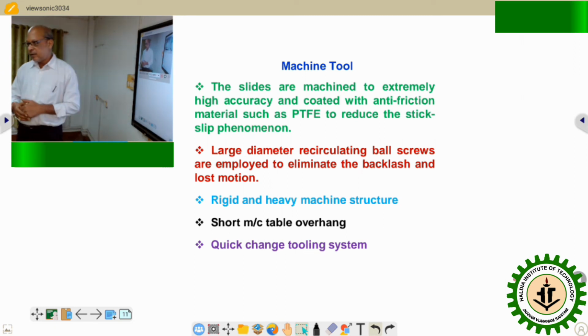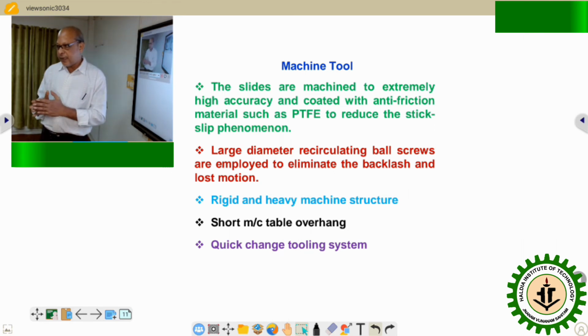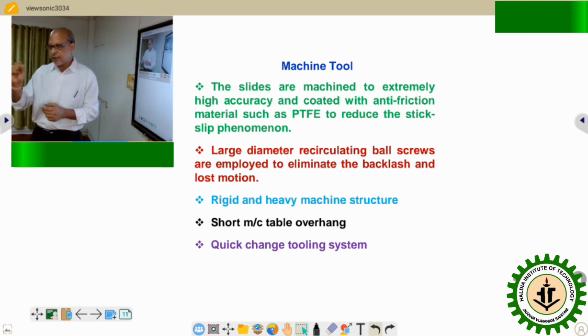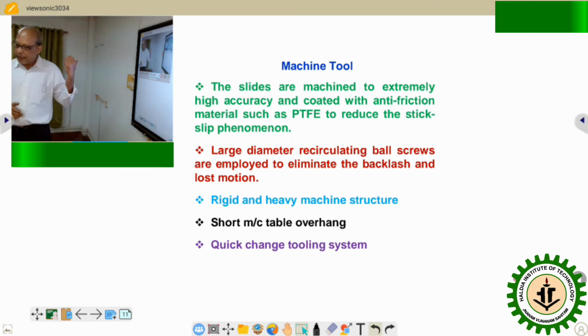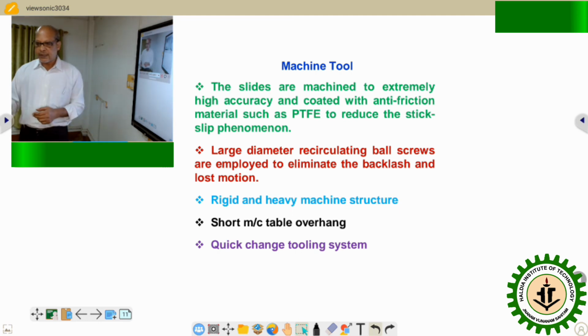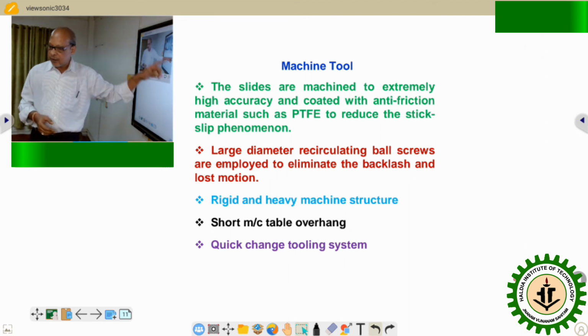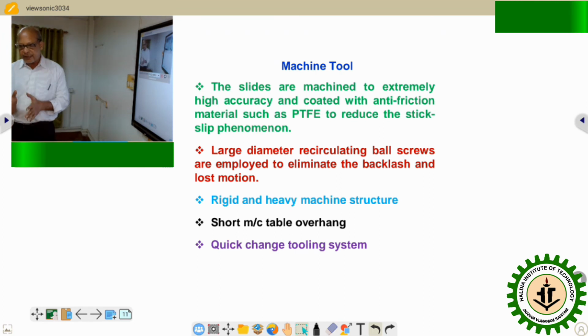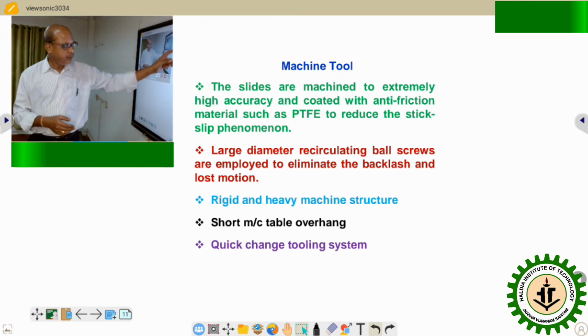So an attempt is made so that the tools or inserts can be replaced very easily and in the smallest possible time. That is why modular tooling systems are used extensively in the tool segment, so that tool replacement or insert modification is possible within the shortest possible time. So this is how performance and productivity features can be addressed by undertaking certain modifications in the machine tool areas.